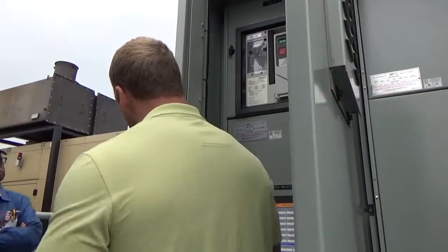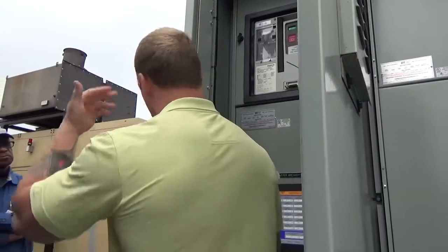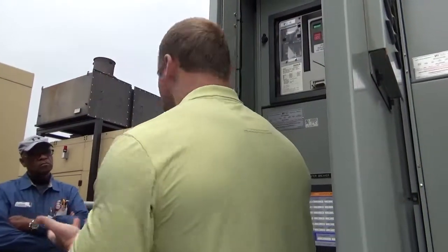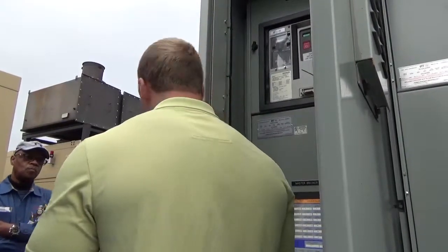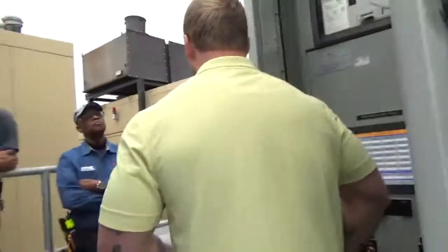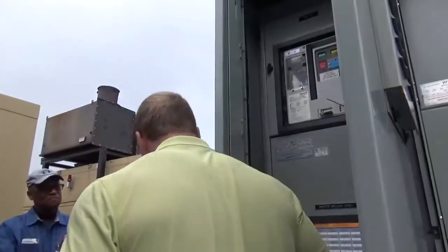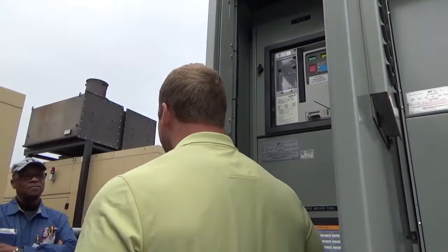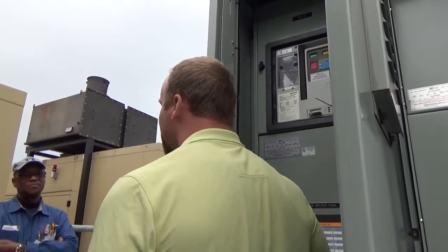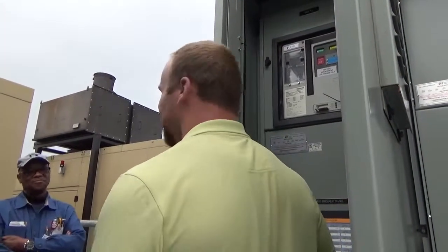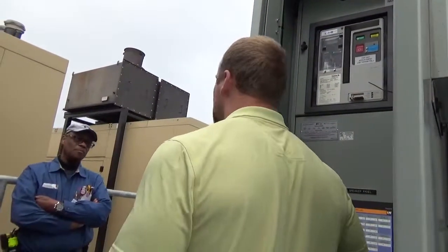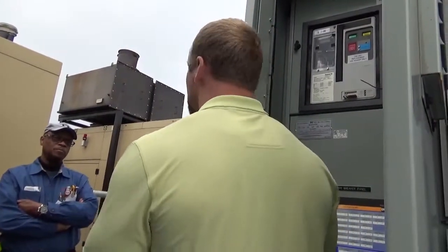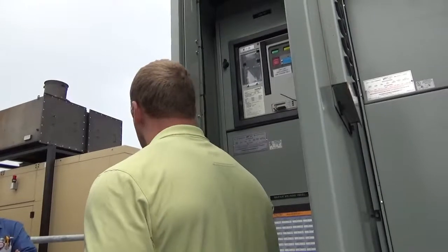Now, what happens if one gen set goes down? The other one will immediately start back up. So you'll have 10 seconds? Another 10-second delay. It'll have a 10-second outage, like you would in a regular outage, unless you have open transition or closed transition here. Take a guess. Open. It's PG&E. The only thing I didn't get. It's PG&E. You see, we got all closed. But really? Parnassus, yeah, 14 of them. PG&E is hard to get closed transition. So even with open transition, you have about a 10-second delay in outage. Even with the same scenario, if that one gen fails, the other one's going to immediately start up. You still only have about a 10-second outage at most.